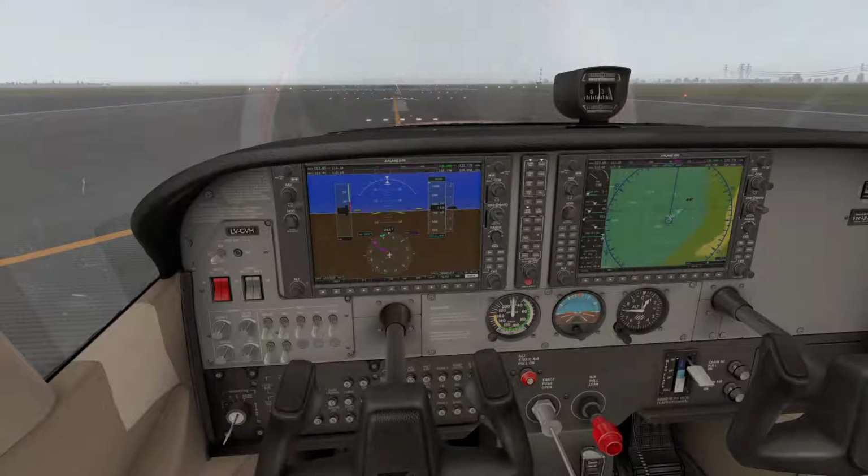That is good. Landing altitude up here on the panel is just about 0 because we're landing basically at sea level. 330 is set. Checking our oil quantity.